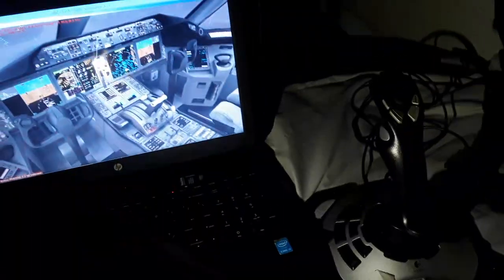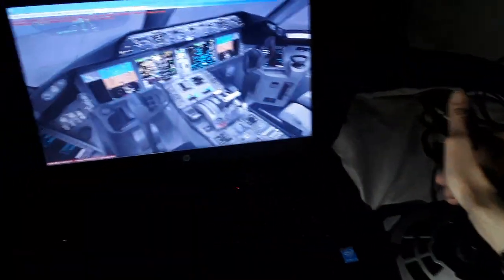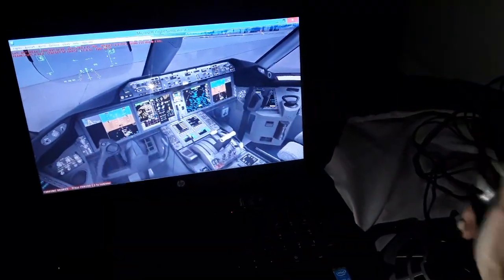So you will see the outside view of the aircraft, how to use the flight controls using the side stick. You can see the Logic Stream 3D, which I use for the Airbus, which we use for Boeing simulation. So you have direct input. The side stick deflection is proportional, as you can see, to the yoke deflection over here. Side stick deflection proportional to the yoke.